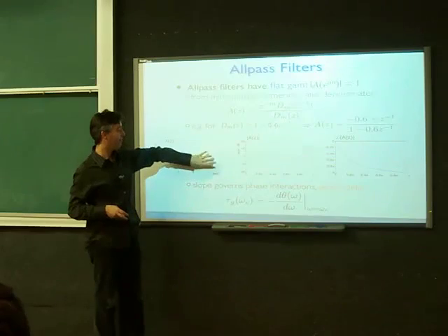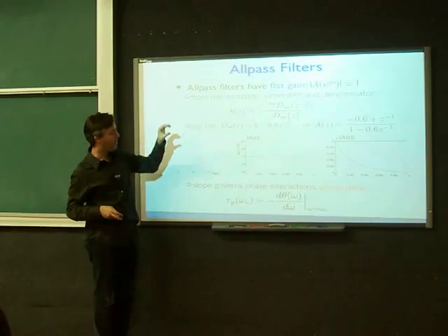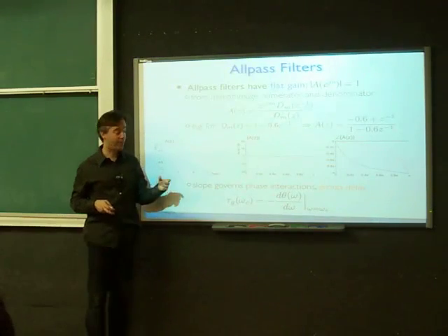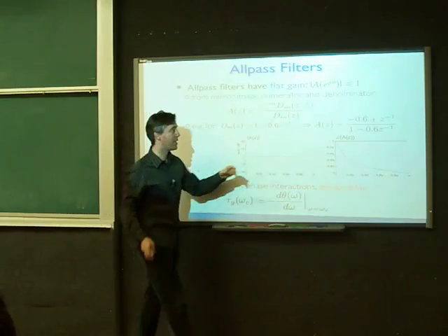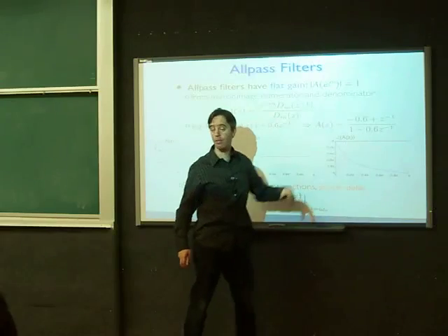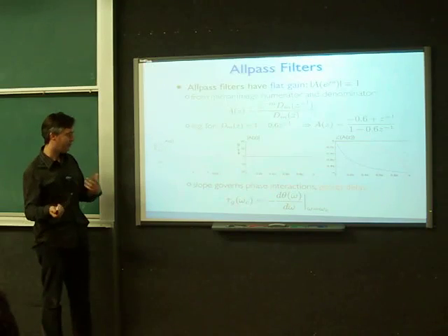So that's just saying what we said before, that the condition for an all-pass filter is to have reciprocal poles and zeros. It turns out that also is equivalent to saying that we have mirror image polynomials. That the polynomials have coefficients in reflected order.